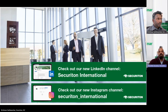And can the beam detectors be integrated with any fire alarm systems? If yes, how, and what additional modules are required to integrate them? Okay. With Securiton, we have an XLM module that is installed in the ILIA, which I showed you in the additional accessories, and that will be connected to our own fire alarm system. Whereas for a third party fire alarm system in the building, we have a relay on the controller, which will release the signals to the relevant fire alarm panel.